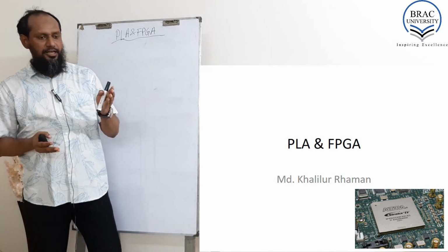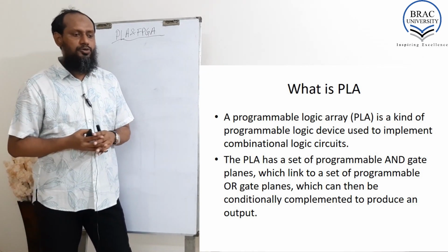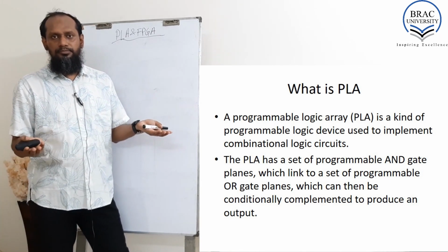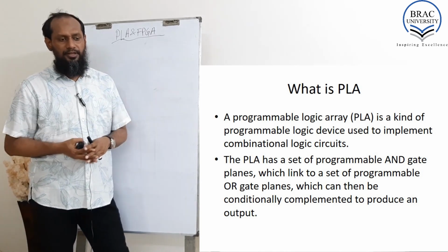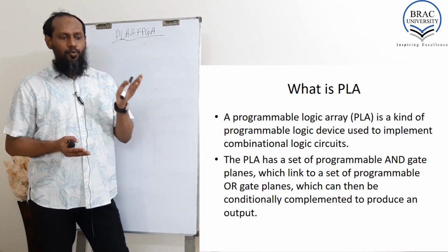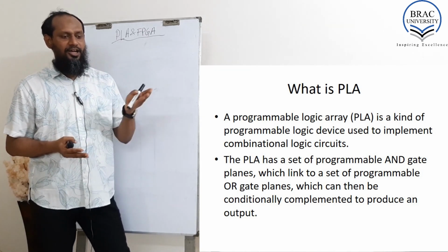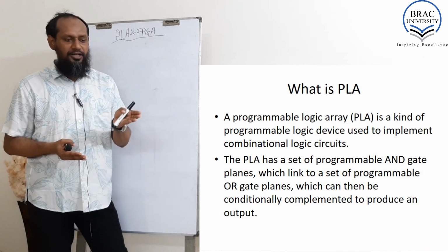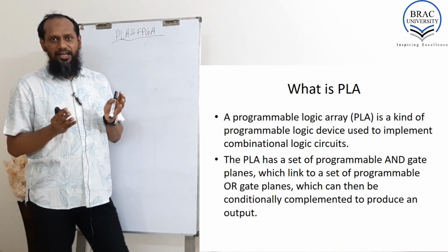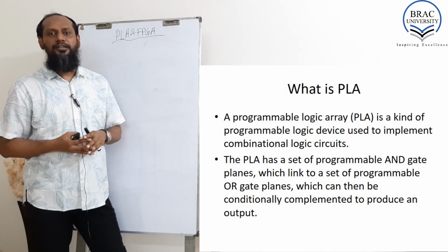A programmable logic array is a kind of programmable logic device used to implement combinatorial circuits, logic circuits, as I told you. So any logic circuit can be implemented in PLA. The PLA has a set of programmable AND gate planes which link to a set of programmable OR gate planes, which can then be conditionally complemented to produce an output. So usually we say it is ORs of ANDs, that means summation of the multiplications.